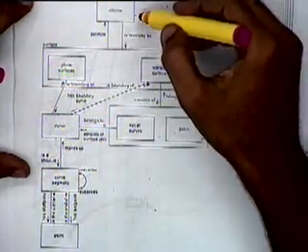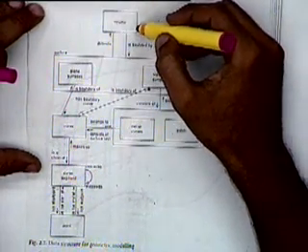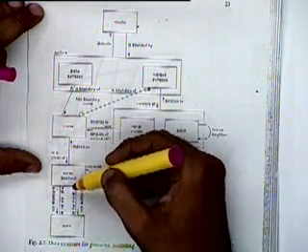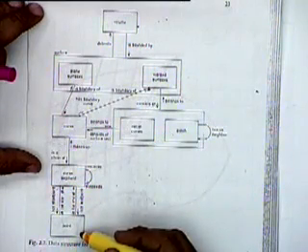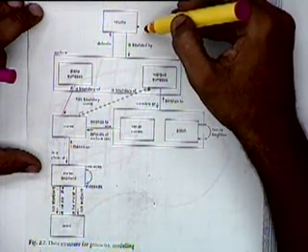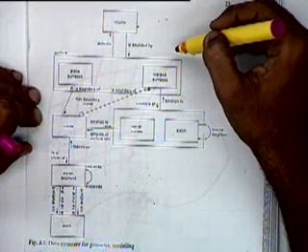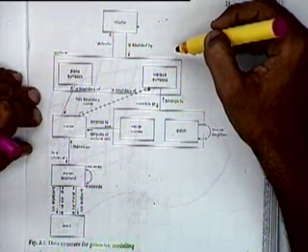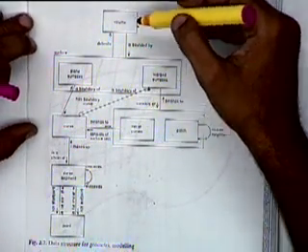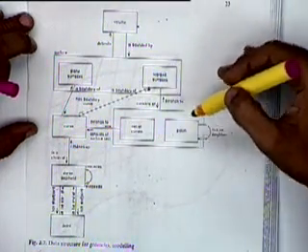So if we want to represent a solid or a volume, this solid or volume will be represented by surfaces which are represented by curves, which are in turn represented by curve segments, which consist of points. If we have to describe solid modeling techniques, we cannot describe them unless we have some idea of how to represent curves and surfaces. The basic method of representing any solid is always going to have methods of representing curves and surfaces embedded in it.